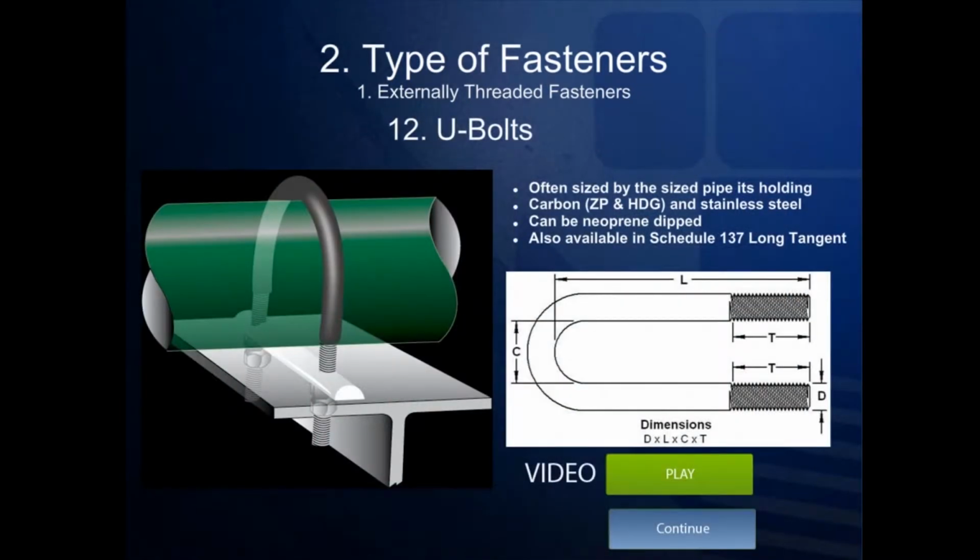U-bolts are typically used for attaching pipe to a support post. Other common applications are to hang wrought iron pipe in mechanical applications such as drainage and fire protection piping in commercial buildings. Oddly enough, U-bolts are measured by the pipe size that they intend to hold, and are available in different stock, which is their diameter sizes. U-bolts are typically found in carbon steel with zinc or hot-dip galvanized platings, and are also available in stainless steel. You should notice that the length of U-bolts is actually measured from the inside of the U.